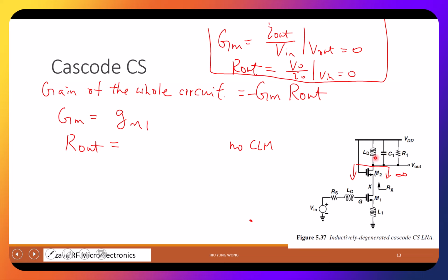Looking up, what is the impedance that you see? He said R1. Okay, then he said LD and C1, right? Both of you are correct. Under what situation is it R1? At resonance. And you're also right because it's for every frequency. So remember this: once you are at resonance, things become so easy. So yes, R1.